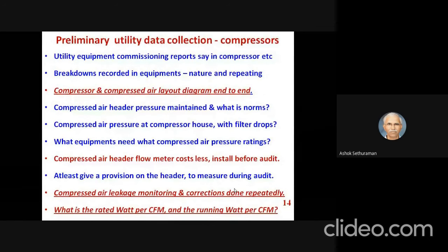Coming to the compressor distribution, you also look at the logbooks. Reading the logbooks and doing an analysis of a random survey of logbooks will say what is the nature of the breakdowns happening in the compressors. Also, you are supposed to have a broad aerial view of the compressor layout diagram end to end. What is the header pressure maintained?